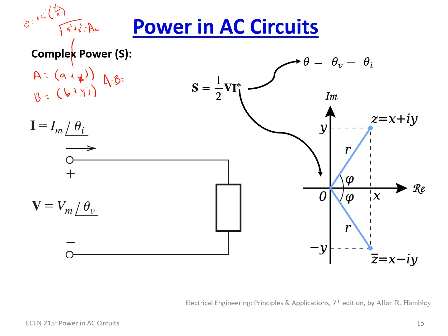So we could rewrite this also as A magnitude times its phase angle, A. And then we'll rewrite this one here as B magnitude, phase angle B. And so A times B, and I know I'm probably boring you a little bit because you've already been doing this for all the homework and everything, but I'm trying to show where this is leading. So we multiply. What do you do here? You add the angles. So you got A plus B.